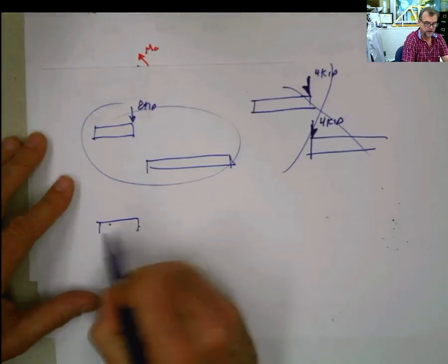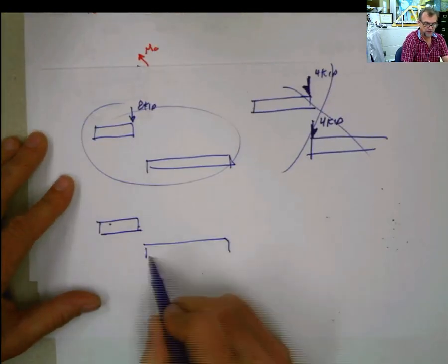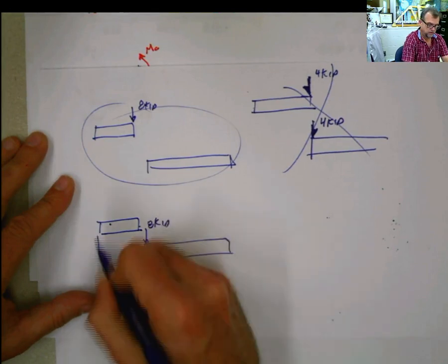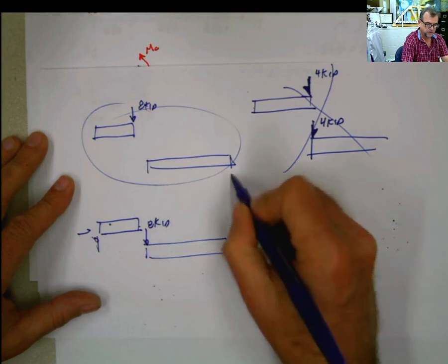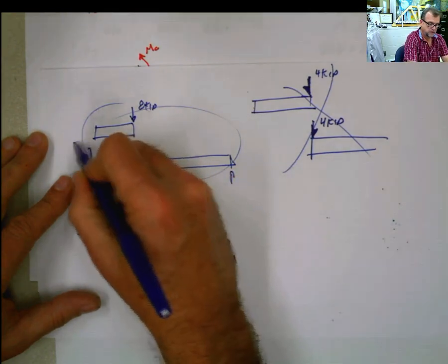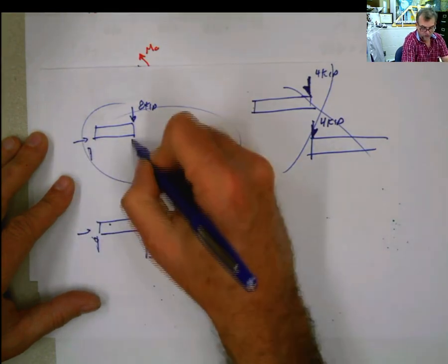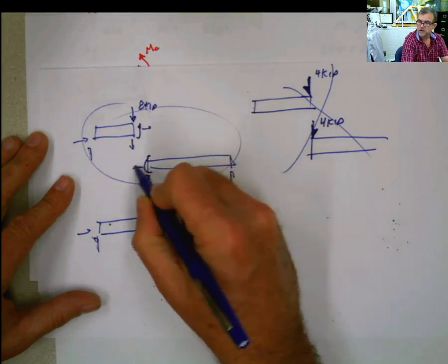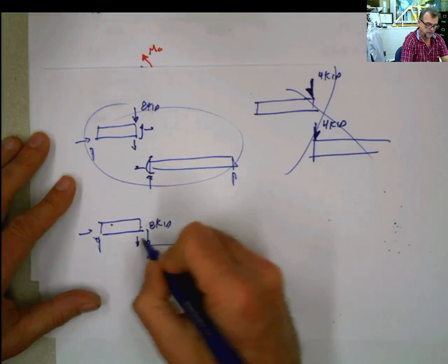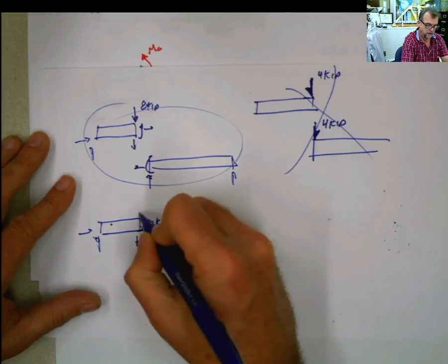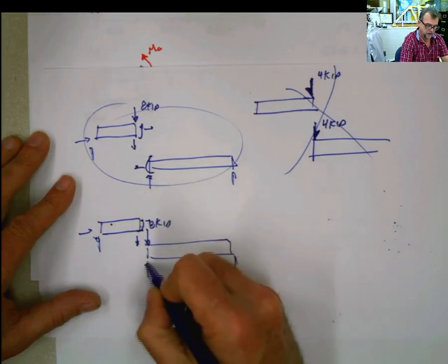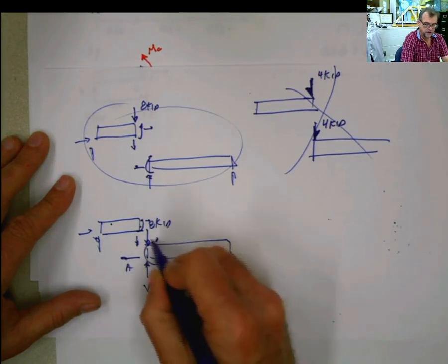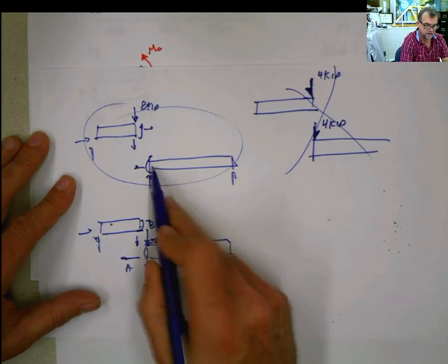And if you say, no, I'm not gonna put the force here, but I'm gonna put the force in this other side of 8 kip, of course here I have my reactions, I'm not putting the reactions, but that is also correct. And of course here in every point I'm gonna have my forces also, and here remember 1, 2, 3, and then I'm gonna have the other reaction here, the shear force, the axial force, and the moment, like that. This is correct, this is correct.